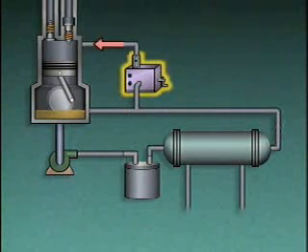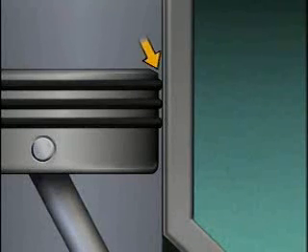The oiler supplies a small amount of oil to the compressor cylinder. In the cylinder, piston rings are used to maintain a seal between the piston and the cylinder. The oil lubricates the piston rings and helps seal the space between the cylinder wall and the ring. Compressed gas systems use auxiliary devices to remove oil or moisture from compressed gas and to prevent overpressurization. Two devices that are used to remove liquids from compressed gas are oil separators and demisters.